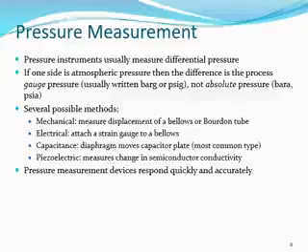How do we measure the pressure? There are different types of measuring the pressure. Mechanically we can measure the pressure by displacement of a diaphragm or Bourdon tube or anything. The pressure creates a displacement of the device, a diaphragm or Bourdon tube, and this displacement leads to a change in the gauge pointer. The pointer in the gauge indicates the location of the pressure in the number, or how much the pressure is.